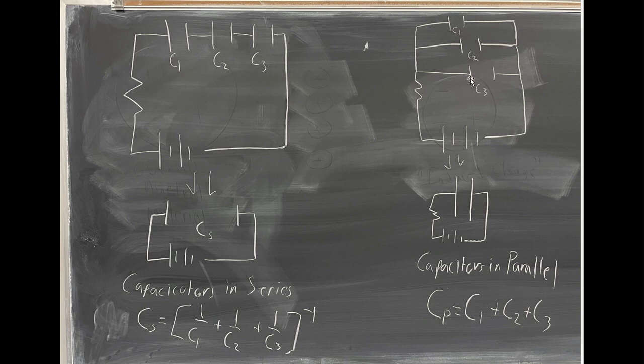If we have parallel plate capacitors, to simplify those to a single capacitor, it's the same formula as if we had resistors in series. For capacitors in parallel, simply add up the capacitance of each capacitor that is in parallel with each other. Well, what this does is it's similar to having one single capacitor that has a substantially larger area, thus allowing it to separate more charge.